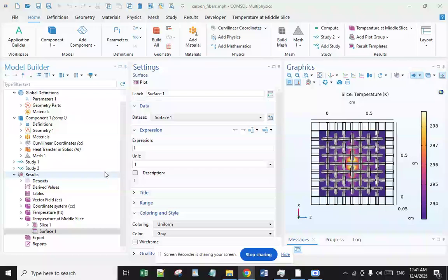for thermoplastic matrix. Product design and process optimization in composite manufacturing is usually conducted via computer simulations in which the heat transfer equation is of particular significance. The thermal properties of the composite material and the contact resistance at interfaces are key properties in the heat transfer equation that need to be measured and inputted in the computer algorithms.